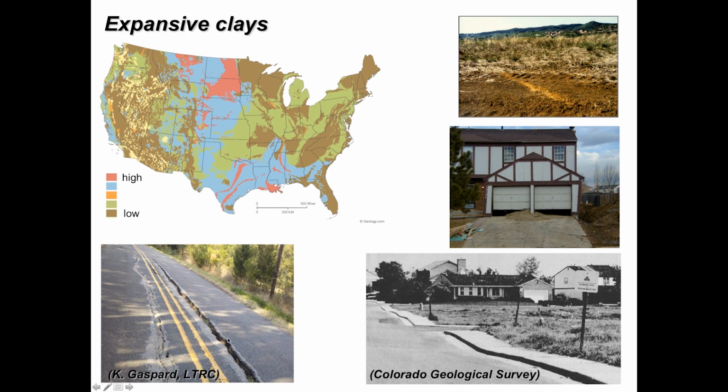And so you can imagine that if that's an expansive clay that swells when the soil wets up and shrinks when it dries out, there's going to be movement, cyclical movement of that material that's really focused near the edge of this pavement, and that's what leads to this longitudinal cracking as that pavement heaves and then settles back down, heaves and settles back down. And this crack changes the moisture infiltration boundary conditions, and so this is a problem that proceeds with time.